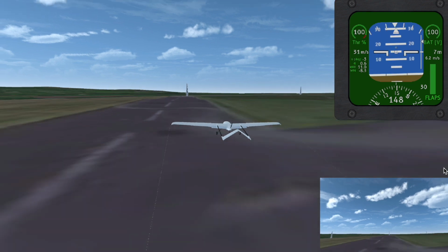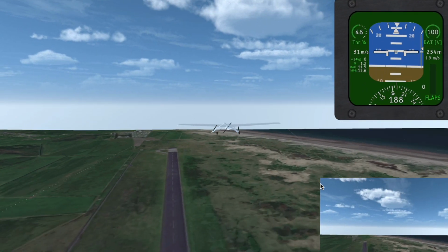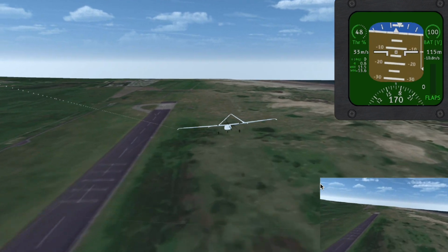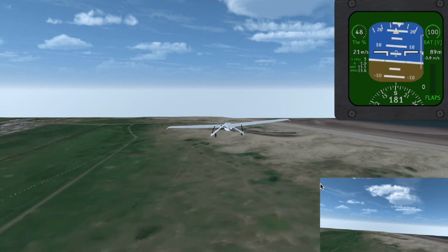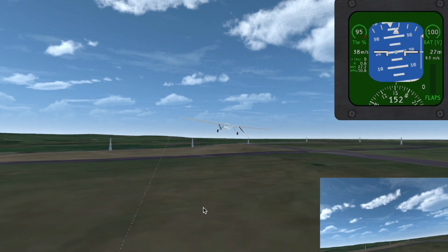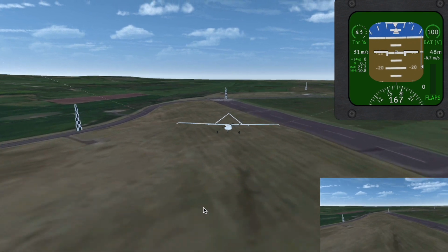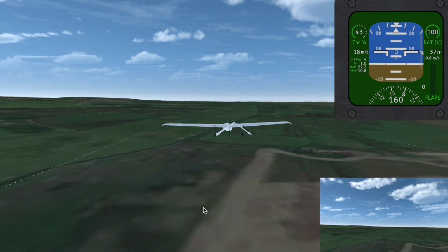At a cruise speed of 20 m/s, achieving steady level flight requires the appropriate elevator trim and throttle settings. For this speed, an elevator trim of 40 degrees was required to maintain steady flight. The minimum trimmed flight speed was found to be 18 m/s, while the maximum trimmed level flight speed was about 42 m/s, needing a negative trim value.